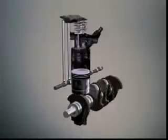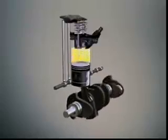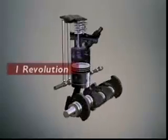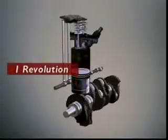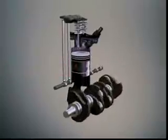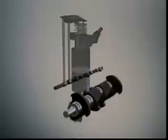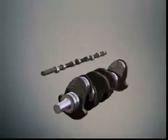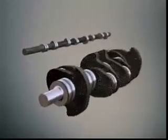In that time, what happens to the valves? They open and close once. So the cams must make just 1 revolution, and if the cams make 1 revolution, so must the camshaft. But in each four-stroke cycle, the crankshaft rotates completely twice, so the camshaft must rotate at half the speed of the crankshaft.